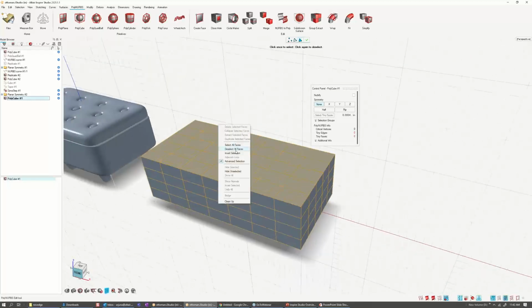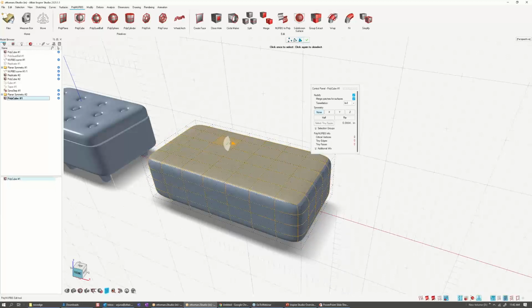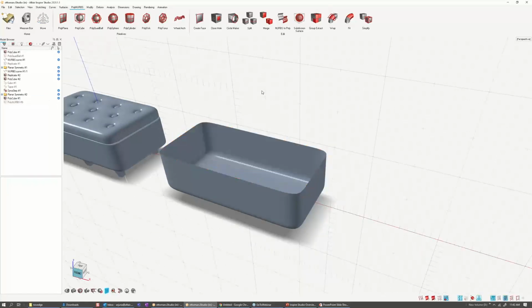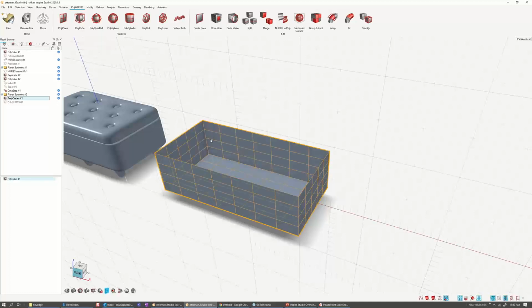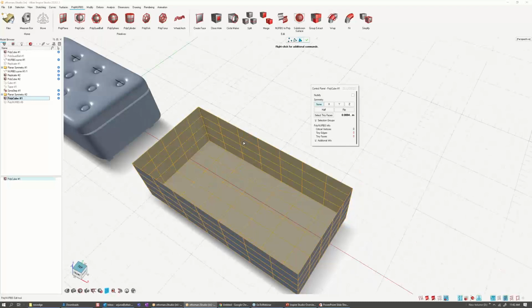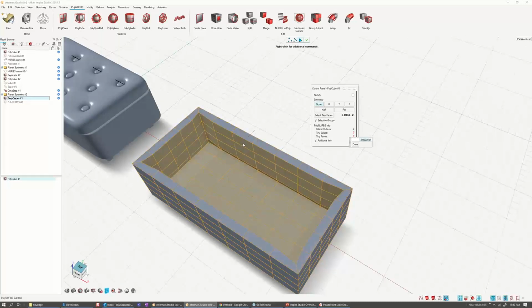So I'm going to do right click, and I have to be in polyNURBS, obviously. So I'm going to do right click, get out of advanced selection, and then do right click and say extract these selected faces. So when I extract, they become a separate polyNURBS object. So if I hide it, you'll see that there's a hole here. So again, we'll do the same thing as we did before. D, select all, and then quickly do an extrusion on the inside. So about 0.5.